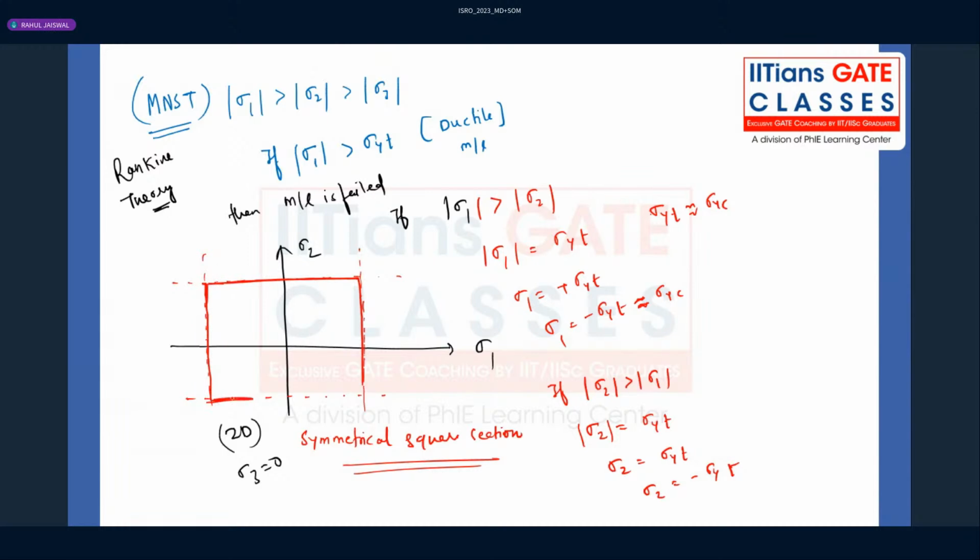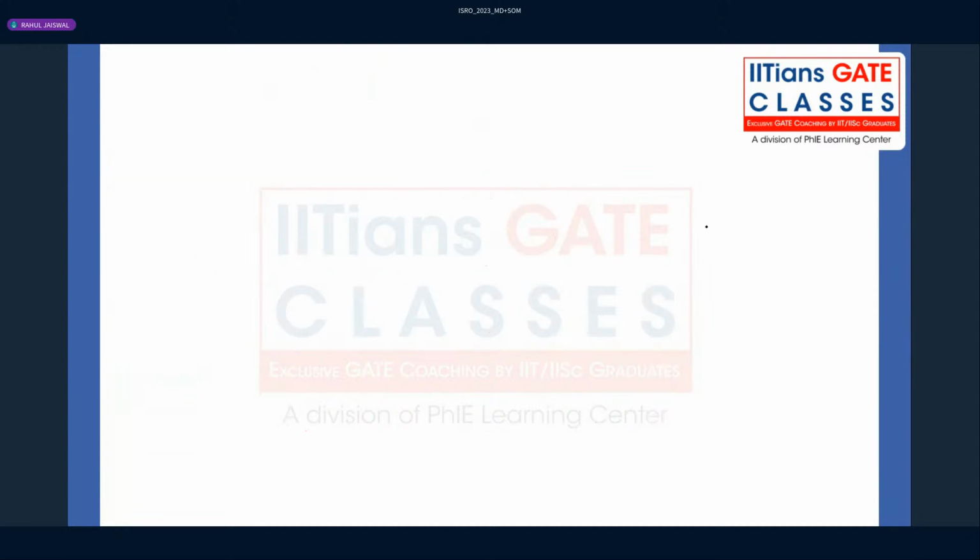Of course, this theory of failure is not very much suited to ductile material, but it is very much suited to brittle material. Now you will ask, what will be the graph for brittle material, right? For brittle material there will not be any yielding. Whatever the ultimate stress in compression will be much higher than ultimate stress in tension, right? So in that case, you will get the graph something like this, something kind of unsymmetrical.